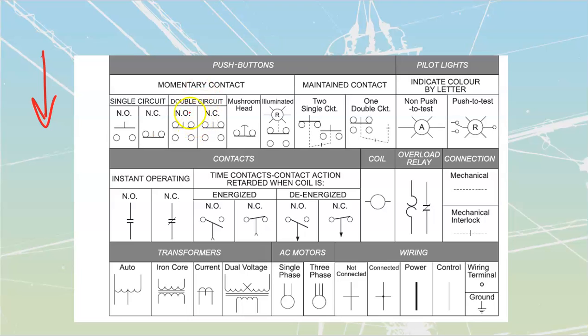We do have some that are going to be double contact, where I'm going to have a normally open, normally closed off of these ones as well. If you take a look at this one that they have over here, the NO and C is all part of the same thing. My normally open would be the bottom two that I would be looking at. My normally closed would be the top two. It's very common where we have that where it changes over from one to the other.